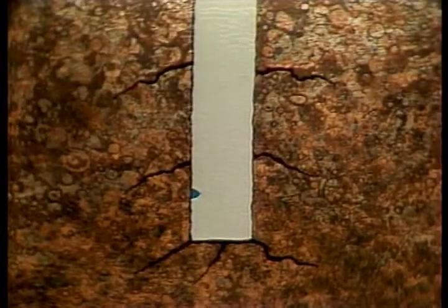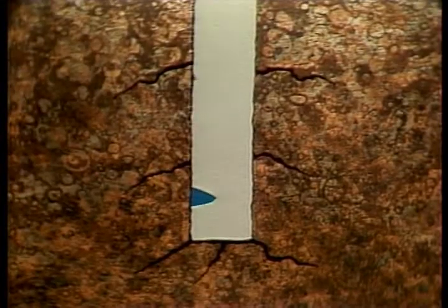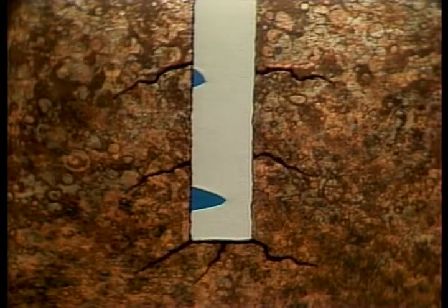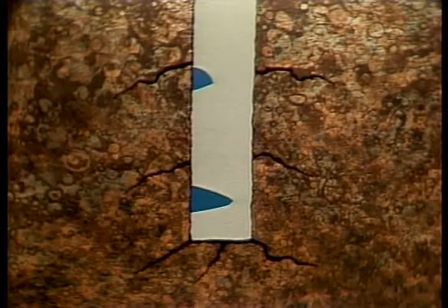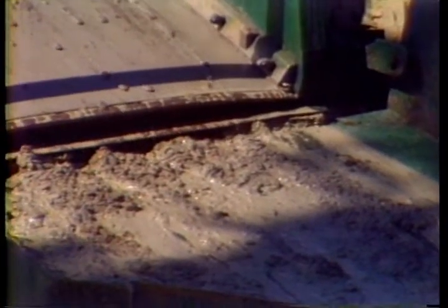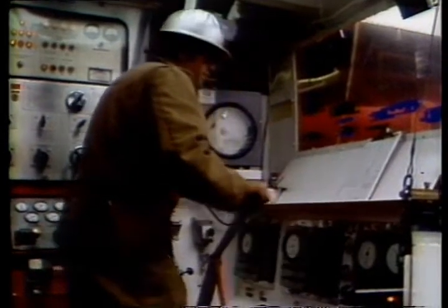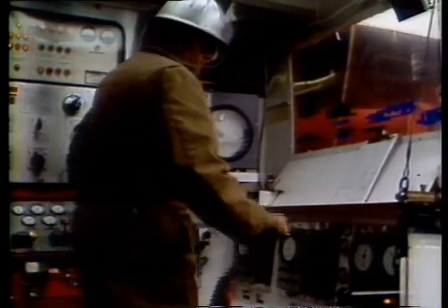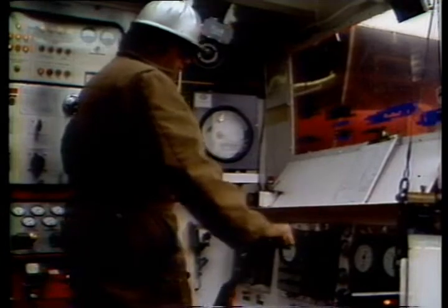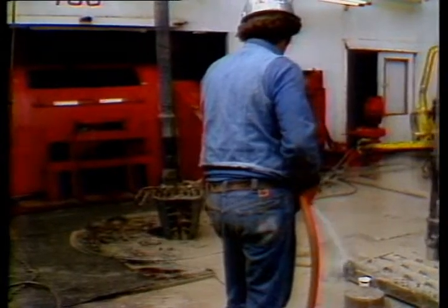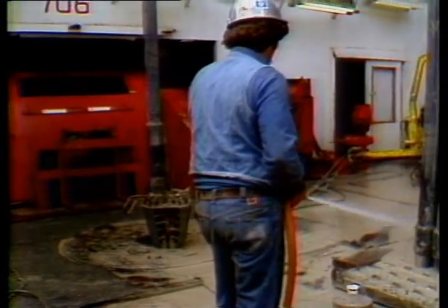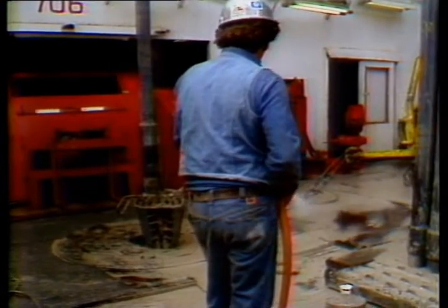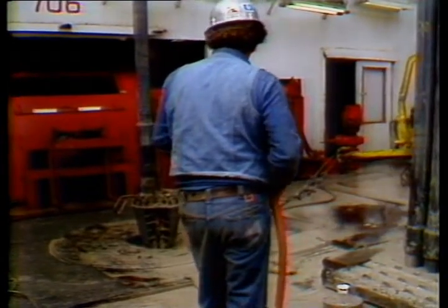Mud weight changes can be caused by salt water or freshwater flows into the mud, changing the solids to liquid ratio. Or it can be due to faulty cleaning equipment leaving too many drilled solids in the mud. Or maybe your driller has drilled into a formation that's adding fine particles to the mud that can't be removed by the solids control equipment. Or it could be something as simple as the drill floor crew washing down the pipe and the floor with too much water and diluting the mud.